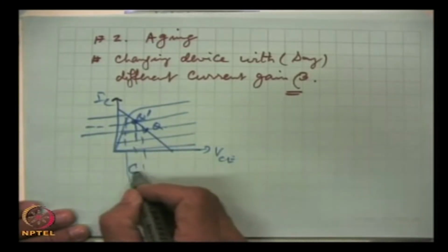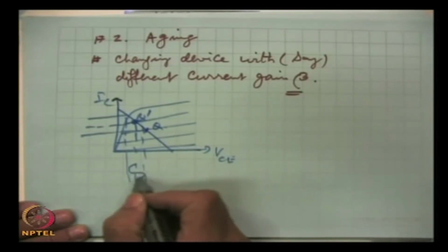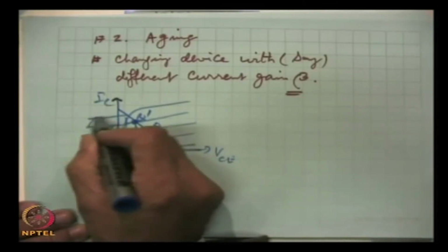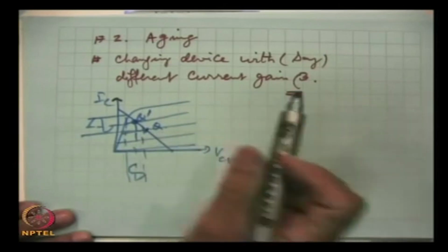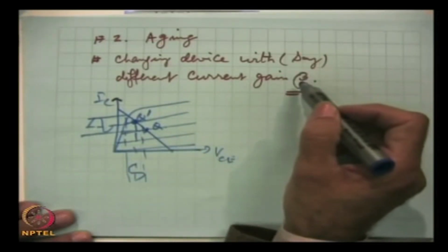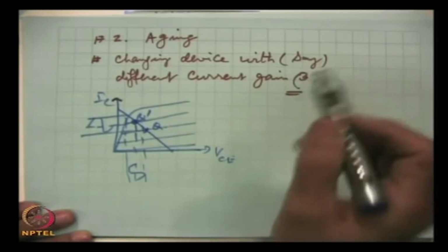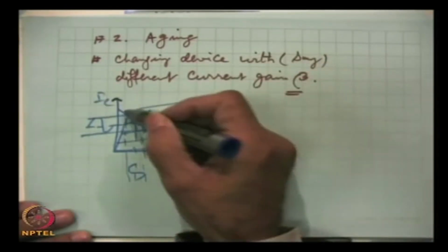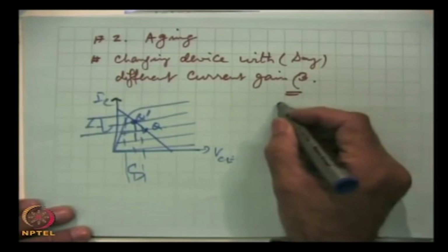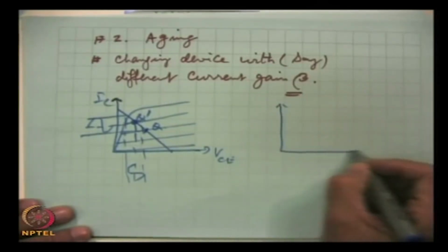So, in spite of the fact that our input was a pure sinusoidal signal, the output may be distorted like that. This will happen when, for example, we replace the transistor with one of higher beta, or temperature changes and it becomes higher. While if beta is less, then it will change in the other direction.